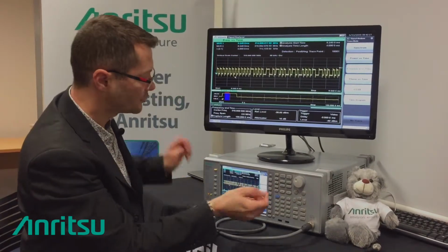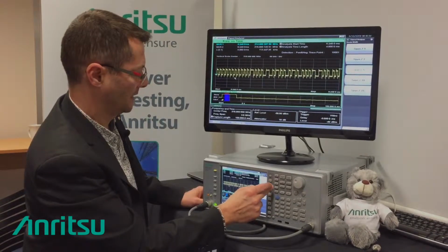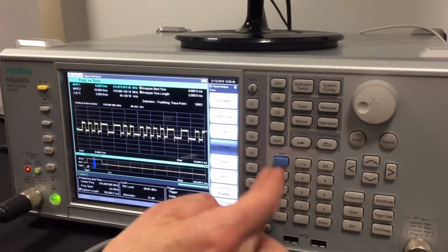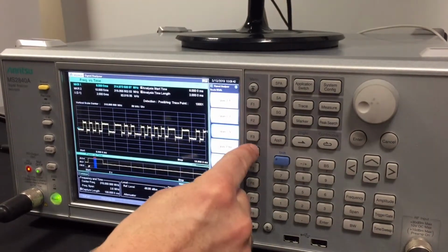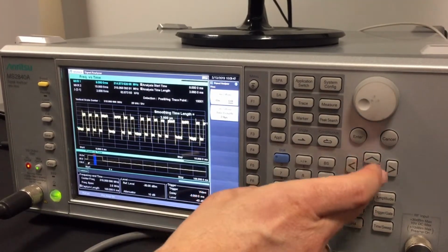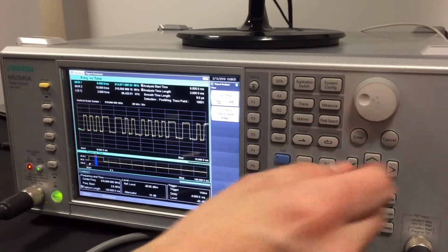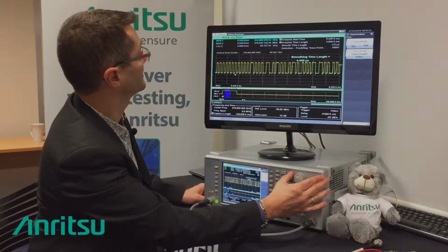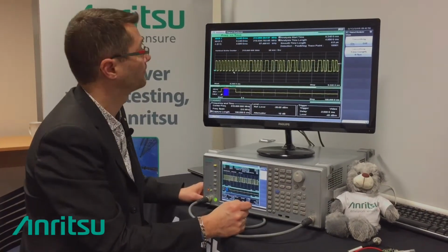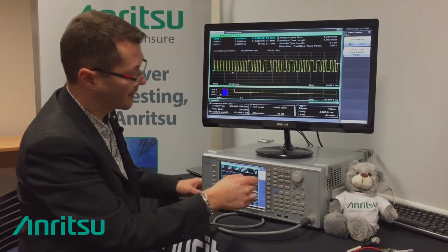I can make a kind of zoom inside this modulation. I will change the vertical scale just to be sure it's higher, or we get a better feeling of what we are seeing. We can make this zone really smaller than this. We can apply some kind of smoothing just to get less spurious. Let's see, like this. We are really seeing now the FSK modulation inside the burst,